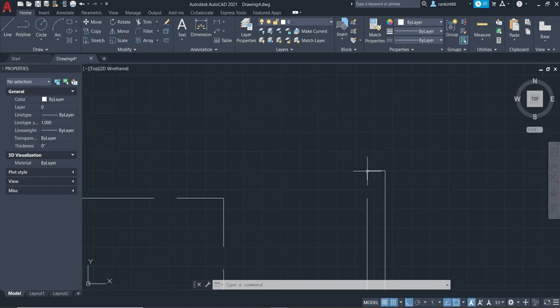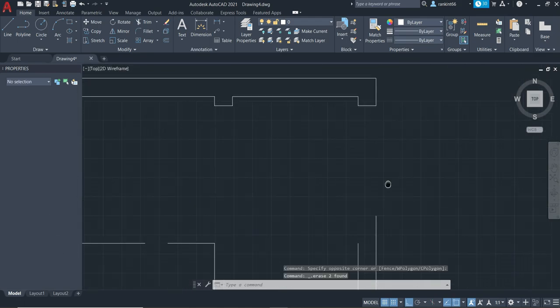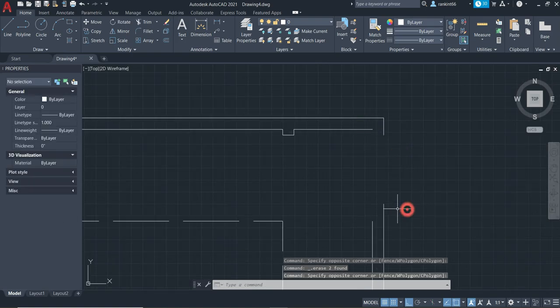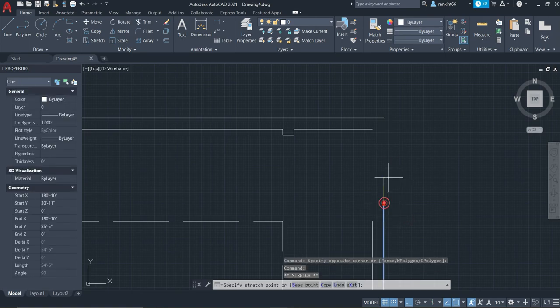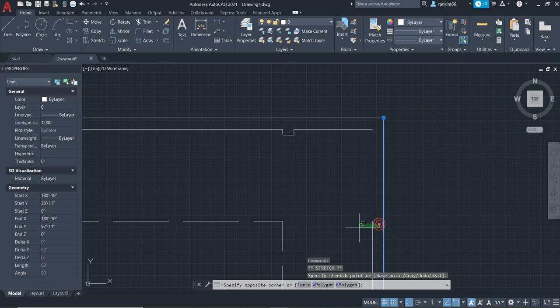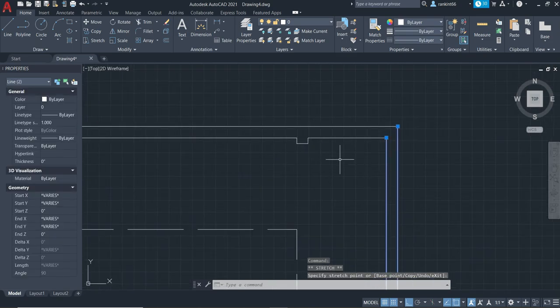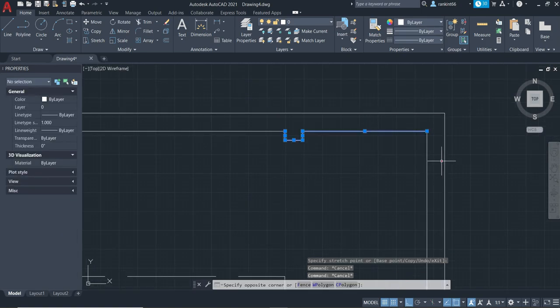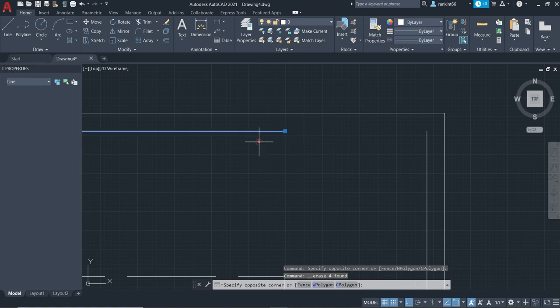So I'm going to go ahead and just start choosing and clearing it out for what lines. So all of these can kind of go away for now. This can go away. I'm going to select this line and I'm going to drag it up and just continue it. Same thing with this line, just so I can have one continuous. I'm going to hit escape. I'm going to select all of this stuff and delete it out, and I'm going to choose this line to stretch it out.